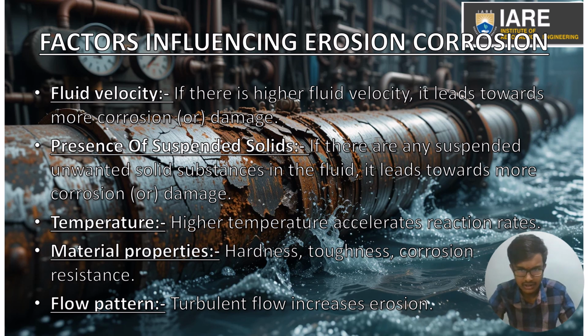And temperature. Temperature also plays a significant role. Higher temperature accelerates the reaction rates which lead towards erosion corrosion. Elevated temperature accelerates chemical reaction rates, leading to faster corrosion processes, and it weakens the integrity of protective layers.